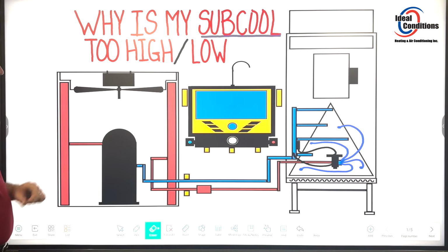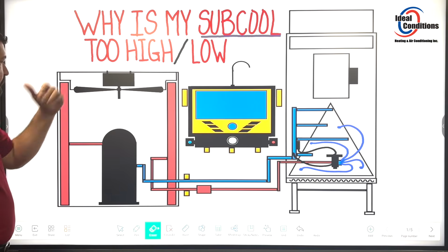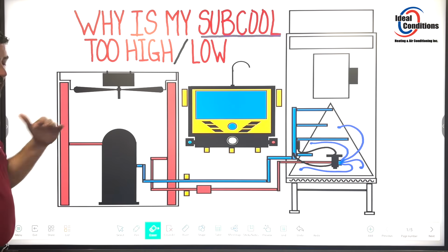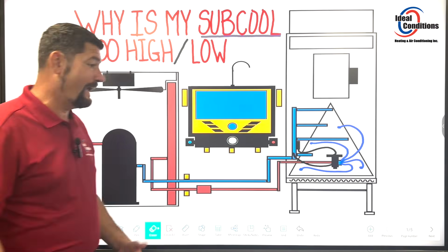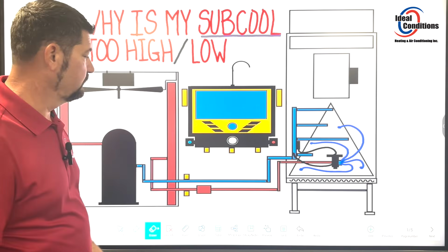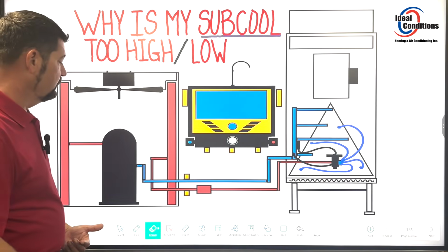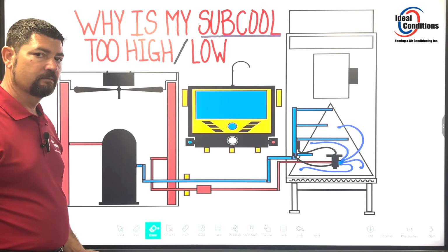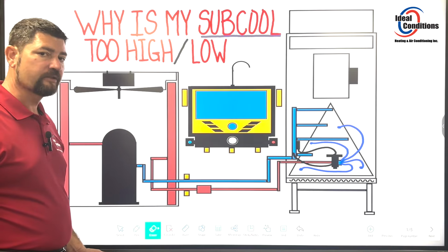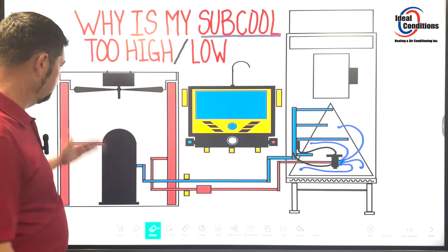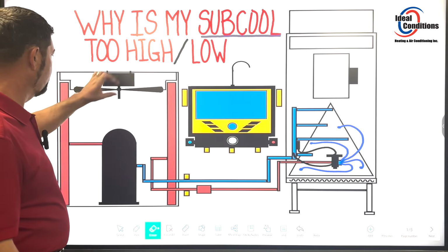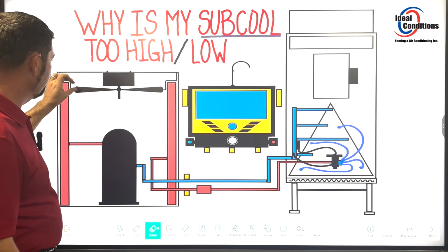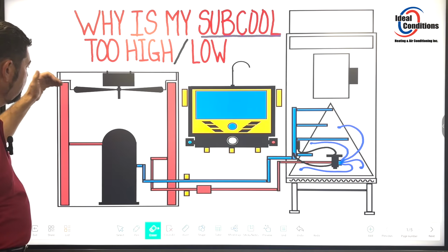And that vapor leaving it, I got vapor going to it right here. So if I have vapor leaving many of these sections of coil because I'm not getting proper air moving across it, then I'm not condensing. That will also reduce that subcool value. So adding refrigerant is not going to help your problem. And that refrigerant that you add will be one of those things where it's like, man, I add refrigerant, my subcool doesn't change, but my head pressure keeps going up. Yeah, because you're adding pressure to the system. You're not creating liquid from it. Clean your coil. Get the fan motor at the right RPMs. Get that fan blade up into that shroud so air can actually get to this top section.